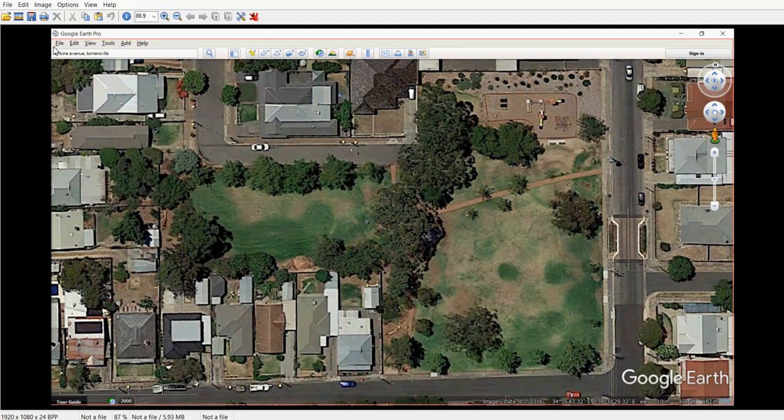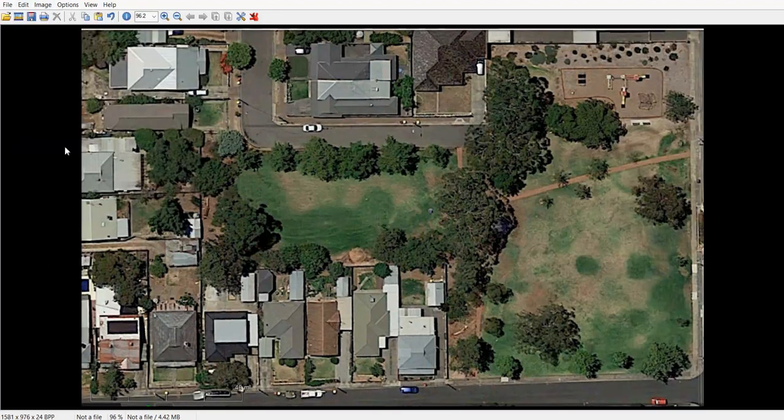It's got some great tools, but all we really need to do is to clean up the image by just cropping out those parts of the image that we don't need. So we must include our scale, but all of the material on the right hand side here is of no interest to us. So we can say edit, cut out. So there's the image file that we want to put in gCADPlus.